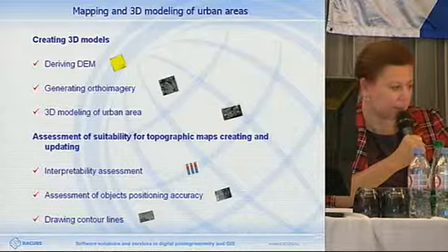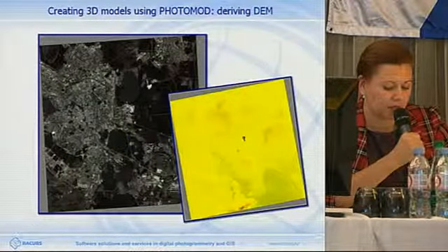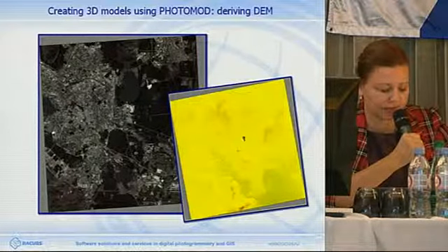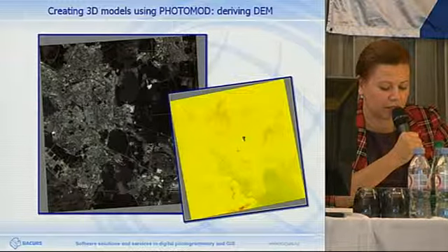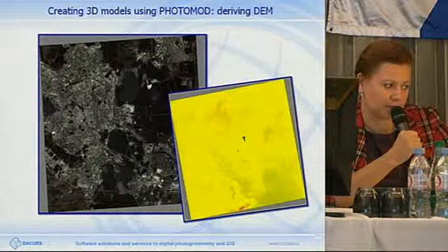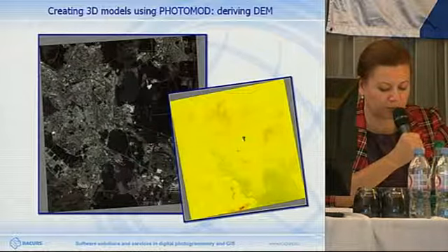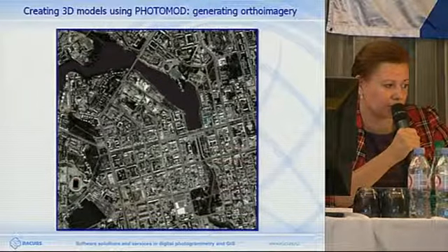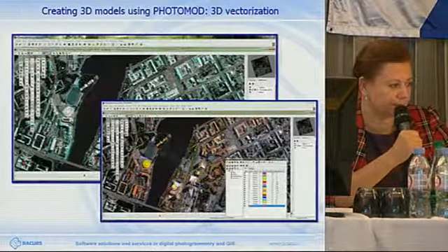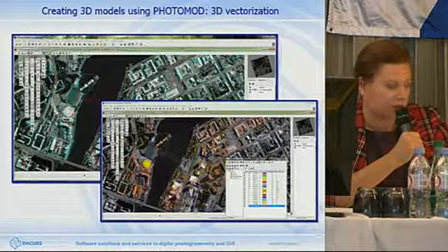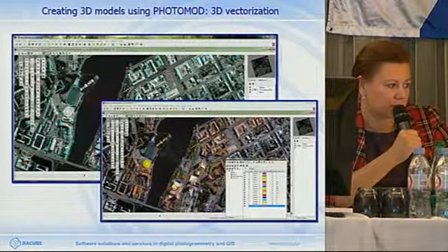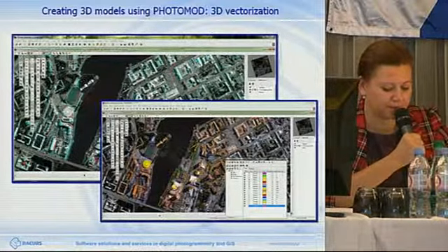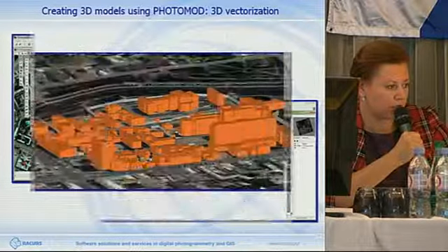To obtain a 3D model, we selected a stereo pair with off-nadir angles of 2.5 and 11 degrees. We built a DEM with 2 meters spacing, and we overlaid orthophoto plan. In parallel, we created 3D vectors. We digitized bridges, trees, a lamppost, some shields.